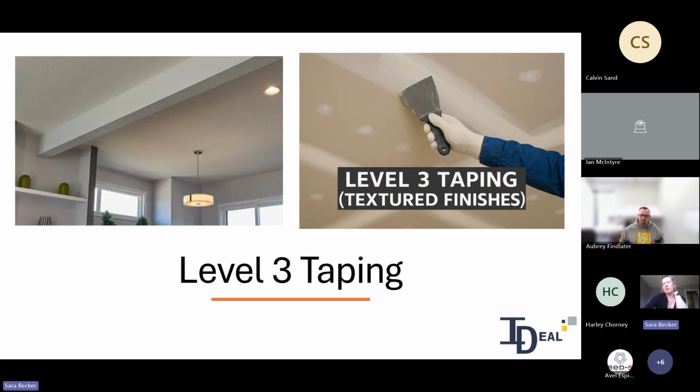Just out of curiosity, sorry, this is behind tile too, right? Or do you go back? Yeah, it depends. Some tile people don't want any mud on the board, so it doesn't bond properly, but sometimes they do want it leveled off. You just wouldn't be able to sand it if you're putting tile over top, or you'd have to do a prime coat to seal it because the dust won't bond with the mortar. Gotcha. Okay.